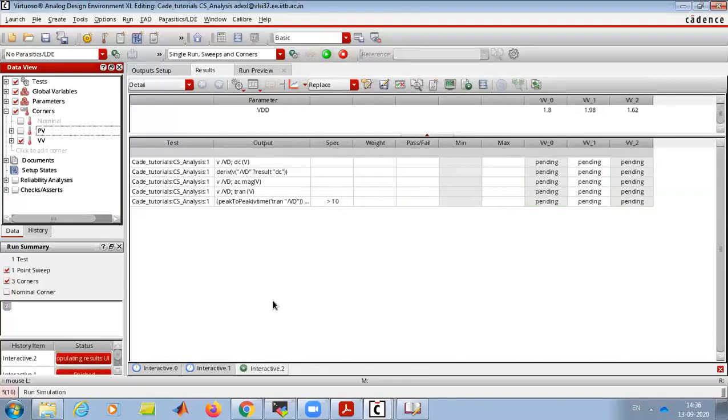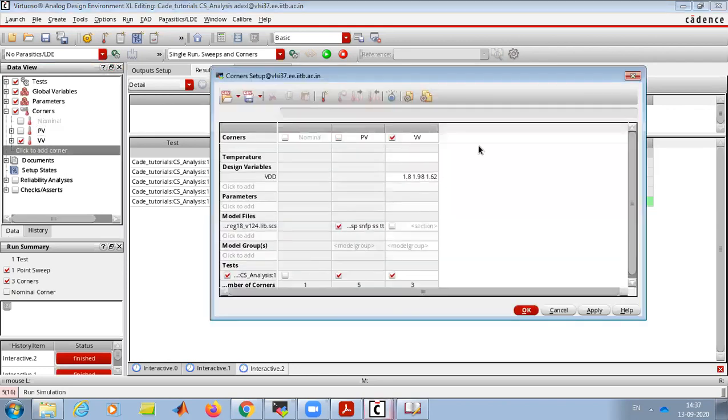It makes the simulation really easy to perform, and you can quickly find out which corner something is not working in. Go to that corner and debug. Here you can see pass. So what it means is that even with supply variations, your design will work. So one thing is this has run for TT. So let's do it again for temperature variation.